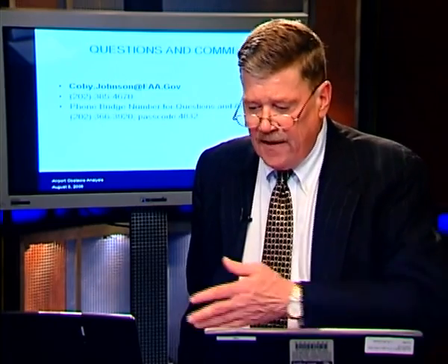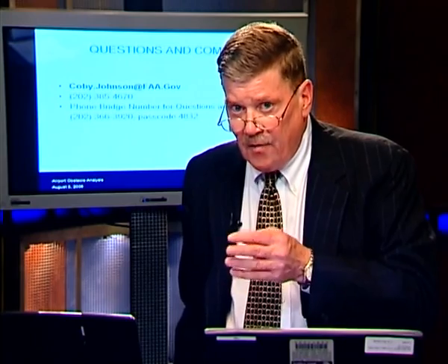Well, that's a good question, Norm. But first of all, when we used to brief this in my old life, we would do this calculation in the pre-approach briefing when we're briefing the 10.7 page. It says 500 feet per nautical mile, which means we've got to have 1,500 feet per minute. Now, on the issue of 1,200 feet per minute, if that's all he's getting out of his airplane, he should not be flying this approach in the first place. He should not have been dispatched at that weight that's going to give him that limiting climb capability. That's all worked out up front in that whole section I referred to as the numbers. He's not supposed to be there in the first place.